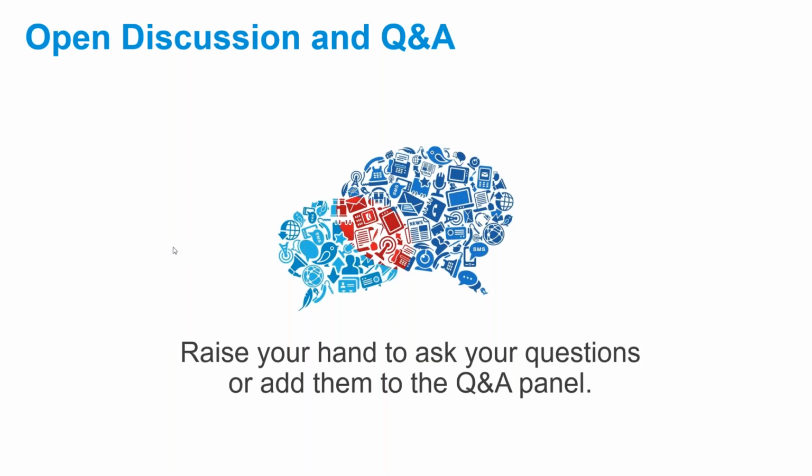Somebody was asking about transfer between US and EU servers. You cannot transfer BIM 360 projects, but you can transfer Plant 3D projects. You can take them with the backup function from the US server and upload them to the EU server. That's absolutely no problem, if this was your question. I'm referring to the question, why is transfer between BIM 360 servers not possible?